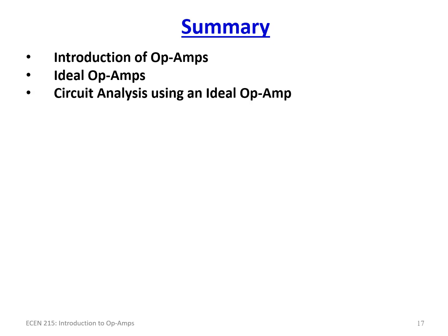And then, of course, we did a basic circuit analysis using an ideal op amp with AOL set to infinity. Technically, you could go back using that same arithmetic and put in the 200,000 volts per volt for AOL, and you're going to see that it approximately works out the same. That AOL is so high that mathematically we still end up with that circuit configuration. We're still an inverting amplifier of minus RF over RN with a little bit of additional gain contributed by the AOL. And then we actually looked at what real op amps do and what they look like.